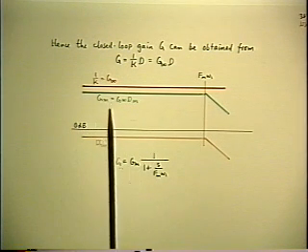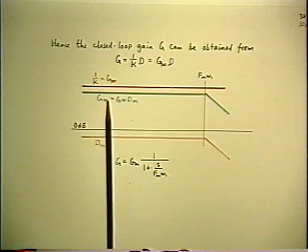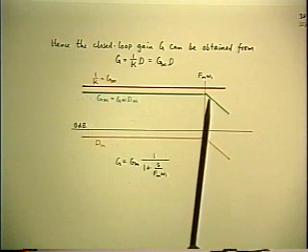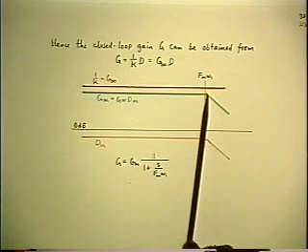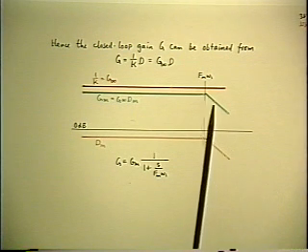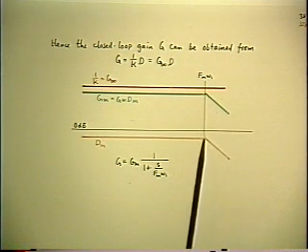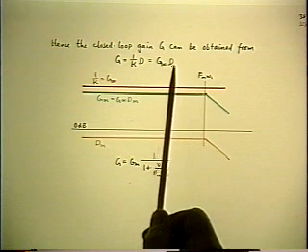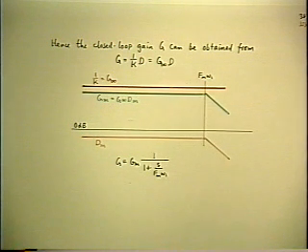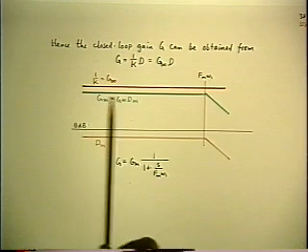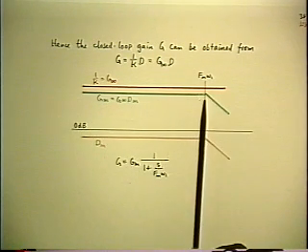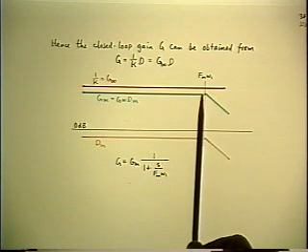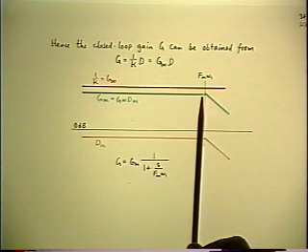And note that the actual closed loop gain that you're going to get, which is the green line Gm, is pretty close to the G infinity, but only up to a certain frequency. And after that, it drops off. That's because the T has gone away, therefore the D has gone away. The discrepancy factor begins to decrease beyond that frequency. So when you have a specification on your closed loop gain, it also has a spec on the required bandwidth. And that's where you have to put this pole. That pole has to be at least as high as the specification requires.